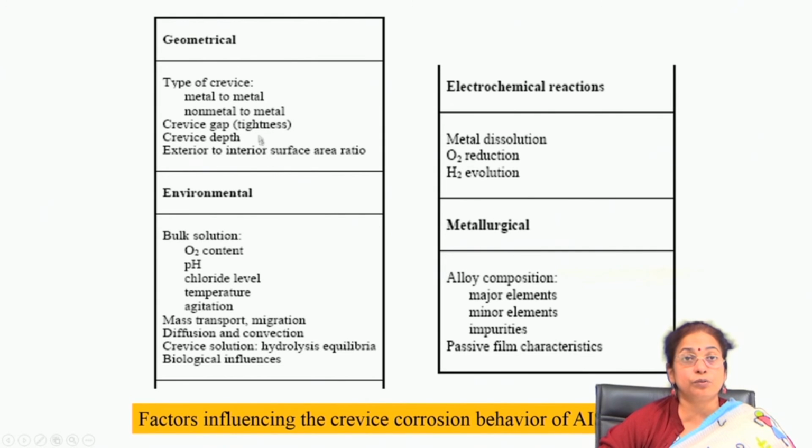You have to avoid conditions where there is a crevice gap or crevice zone in the metal. You have to be careful to avoid silting, and if you flow the air or water properly so that the region is properly protected, there is less probability of crevice attack. You can also get rid of crevice corrosion by proper choice of material.